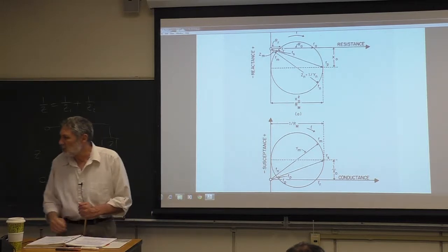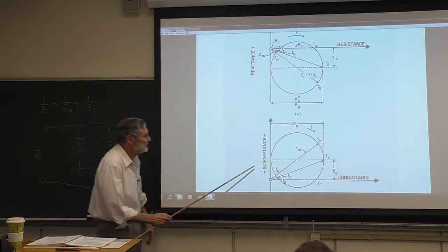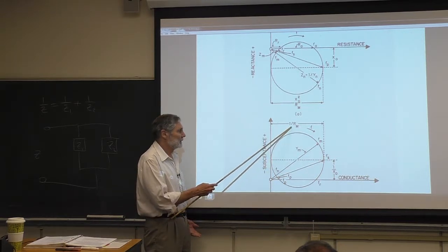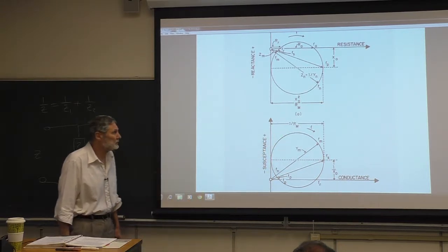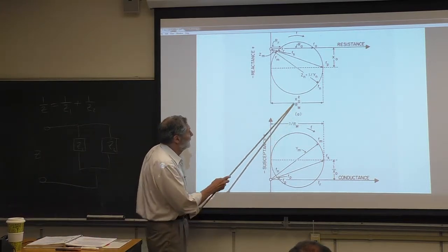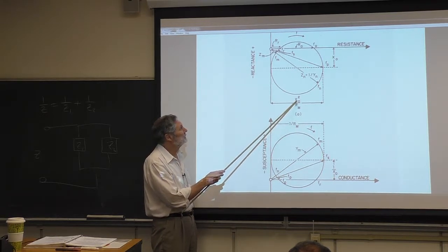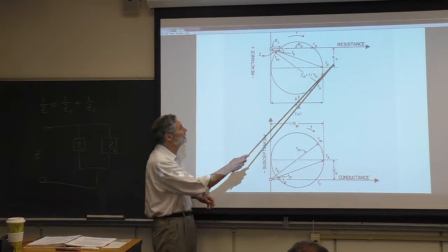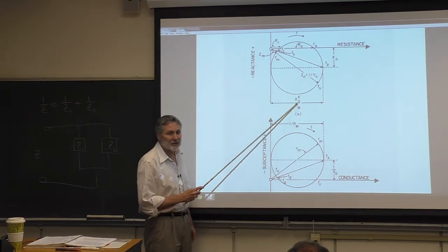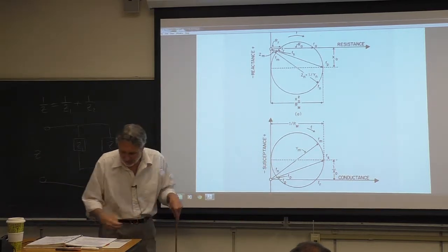Okay, so one advantage of admittance you can see immediately here. Look at the diameter of the circle. Here it immediately gives you a mechanical quantity, 1 over the motional resistance. But here, what does it give you? Well, you've got to worry about this reactance quantity here, the reactance associated with the center of the circle, X naught. So that's an advantage right there to admittance, and there are other advantages, but you can see one straight away right there.